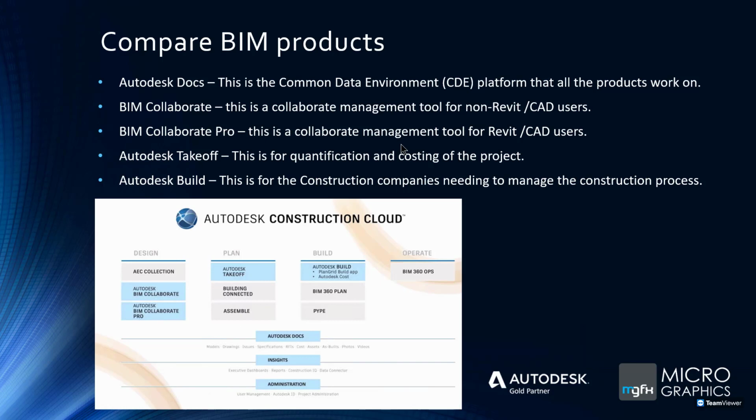So that is based on the 3D model. The takeoff is also based on 2D, linear, count objects and areas, and they can create formulas based on the totals of those lengths, numbers and areas, and get a result. So if those lengths, counts or areas change, the results update. It's just adding formulas, etc. But that's a whole different discussion.